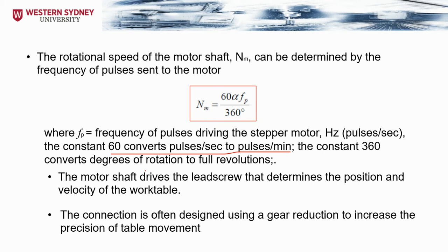Now, why do we need torque? Because we always have a cutting operation, and this requires some force for the table when it's moving. So you can see that we have two different advantages for the reduction gearbox. It's always going to reduce the RPM, so we have more precision for the movement, and it also adds some force when moving the table.